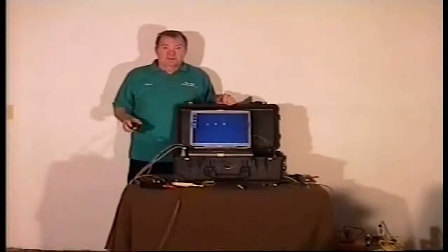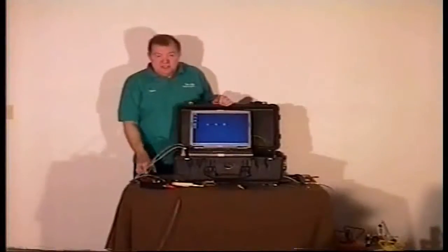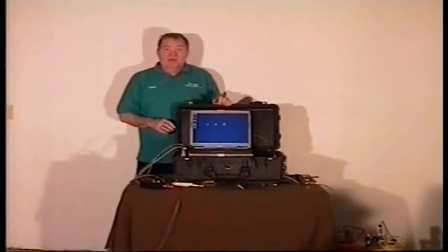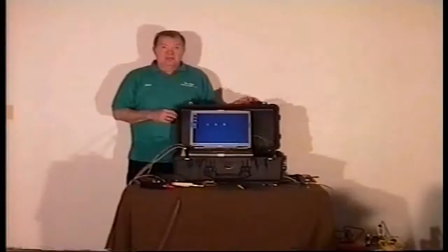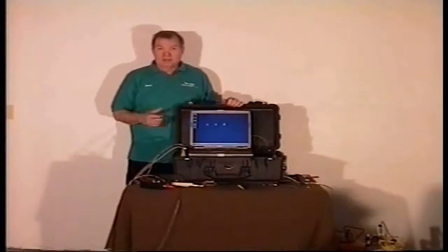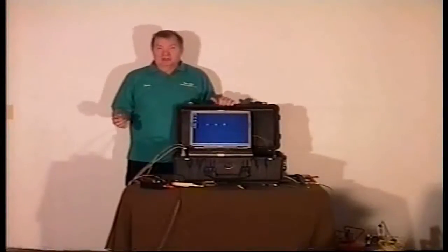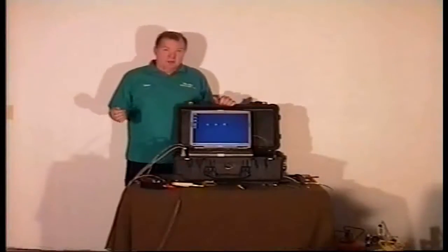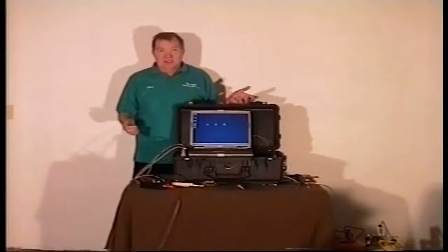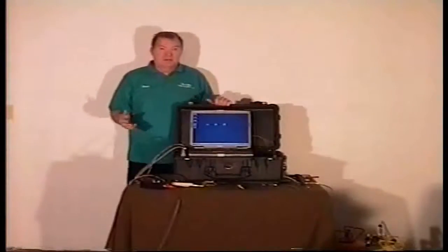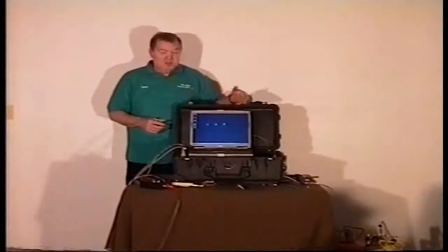I think that pretty well covers the operation of this analyzer. This is an infrared system. Keep in mind the infrared analyzers completely isolate the detectors and the IR sources from any of the sample gas. That's the way they're a lot more rugged, a lot more reliable. If you have a case of contamination or water contamination, the sample chamber can actually be removed, it can be cleaned, it can be put back together, and this is something that you can do out there in the field, as well as calibrating.